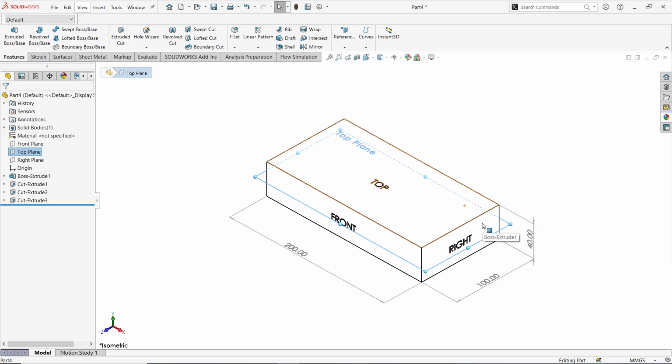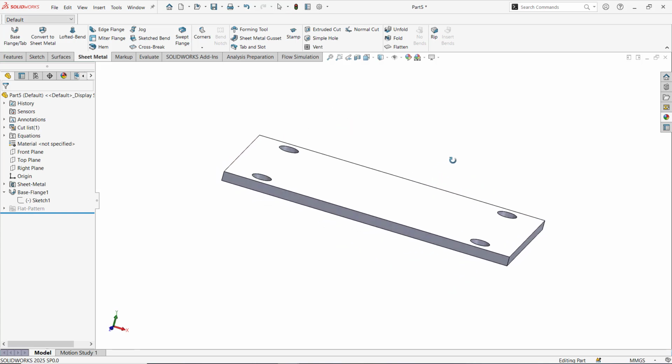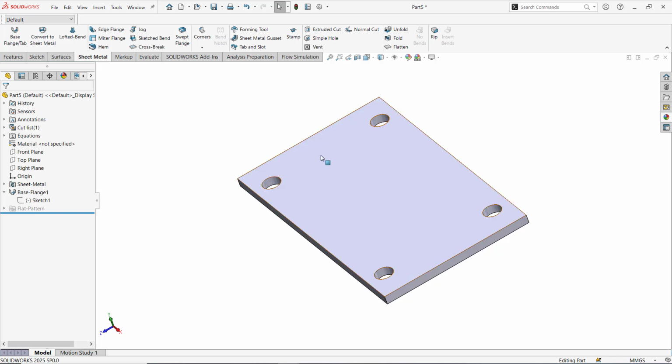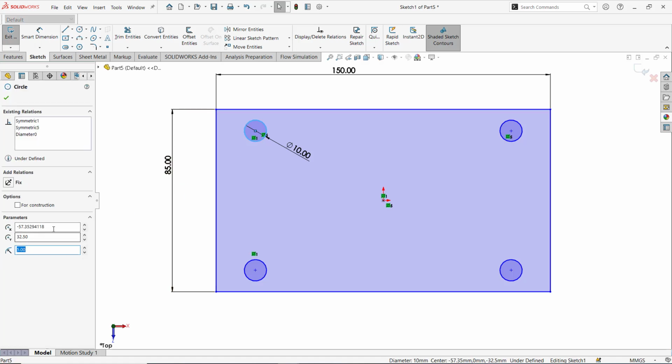Your orientation determines which plane is easiest to start your sketch on, so it's important to use proper dimensions when you are selecting a plane. Another tip is to choose the plane where the dimensioning will be easier. For example, you are making a flat plate with holes. Sketching on the top plane makes sense because you can position the holes using simple x and y coordinates.